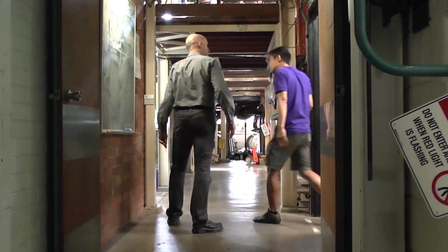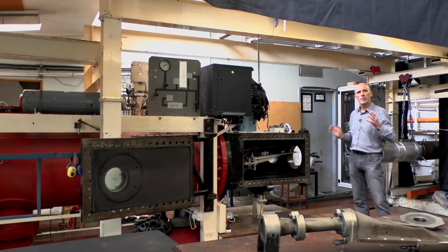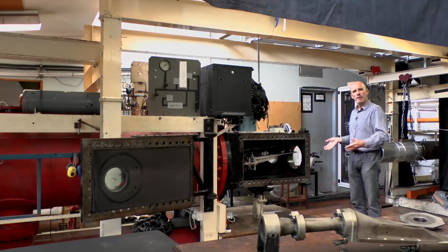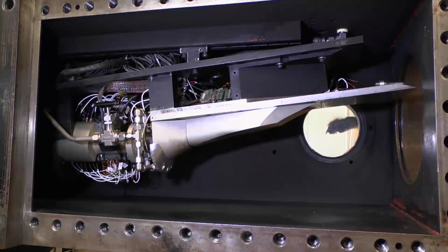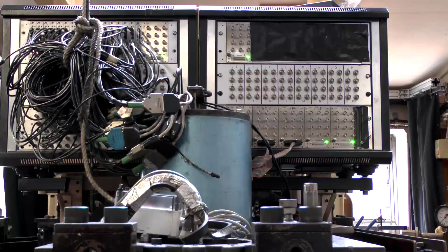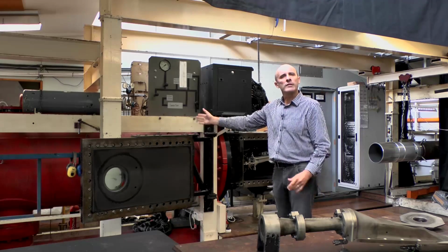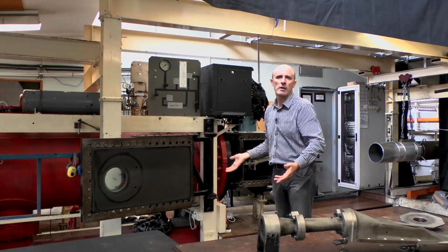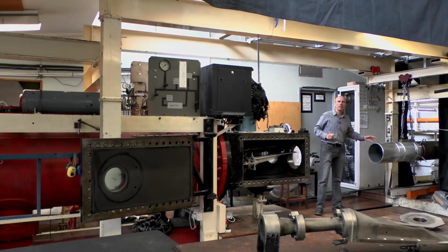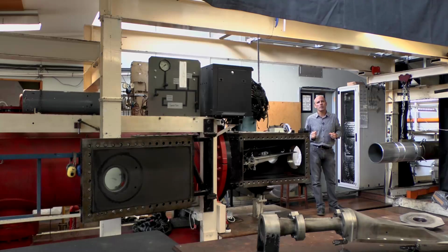So let's just go up the tunnel and see what's going on. Okay. So here we are at the business end of the T4 shock tunnel, and in front of us we have the open test section and our scramjet model. So above the test section we have our high frequency electronic equipment that we need to take our data in the short test time. And at the end of the facility we have our dump tank where we collect all the gases after a shot. And of course here is our hypersonic nozzle which accelerates the gases to hypersonic speed, and then they pass through the test section and our scramjet.